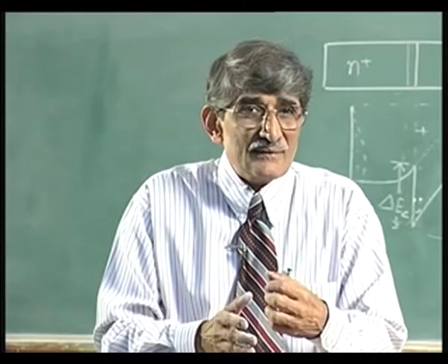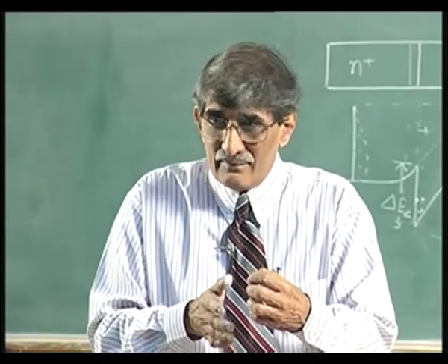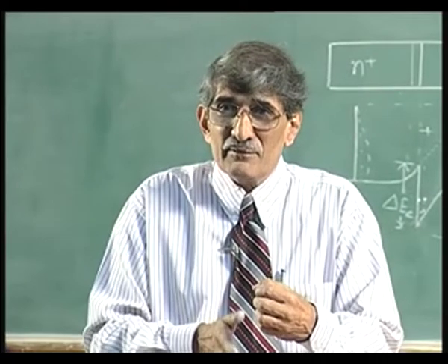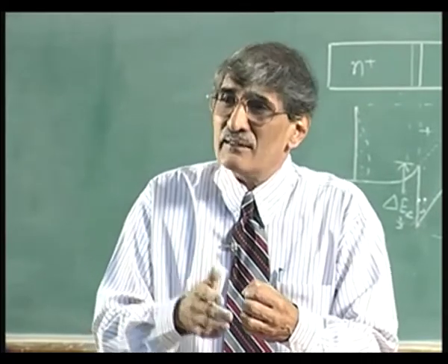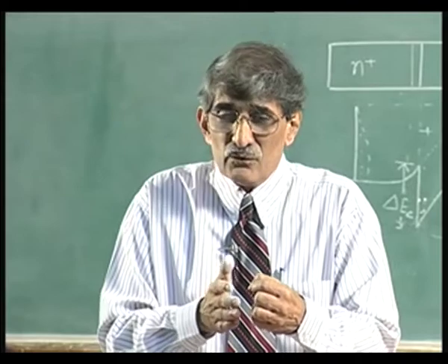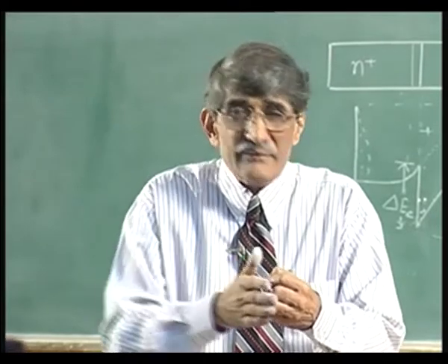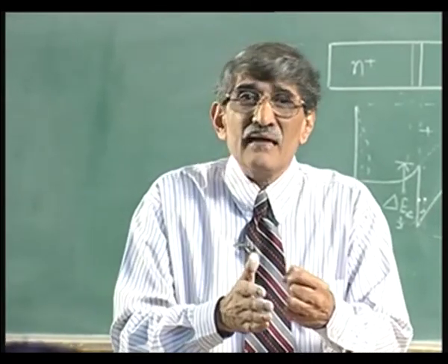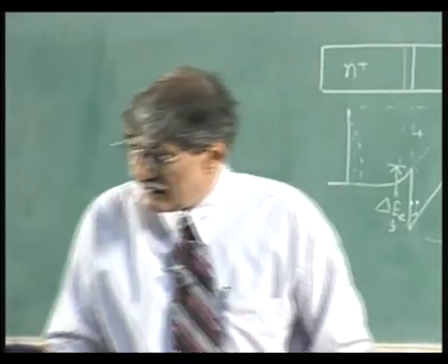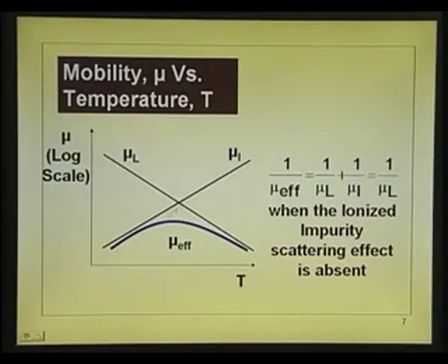At lower temperatures, this poor electron which is moving at a certain velocity does not have that much energy, that much velocity. So, it actually gets scattered more, deflected more. The chance of scattering is more when you go to lower temperature. That is why at lower temperature the mobility decided by impurity scattering is lower. Okay. And this is the other one.